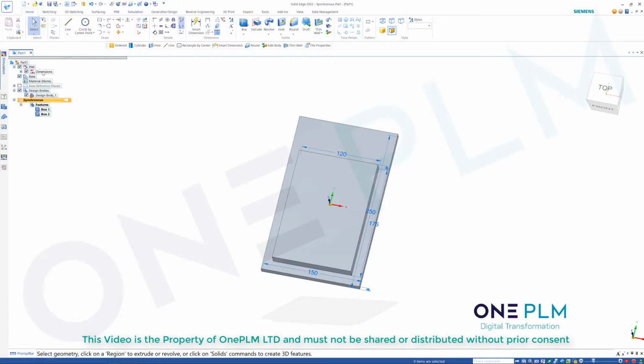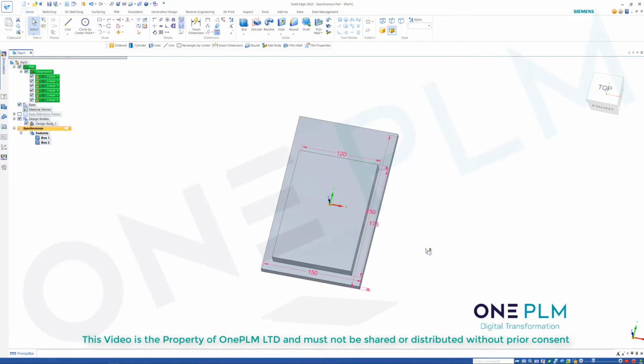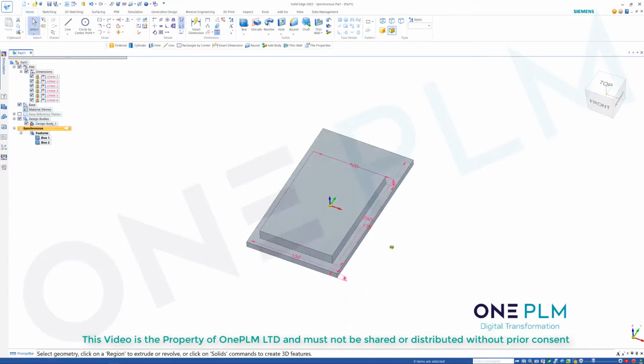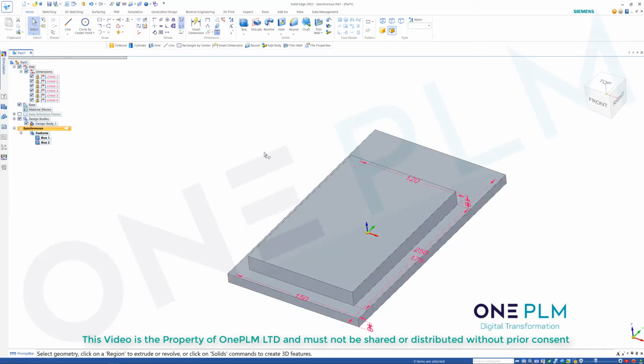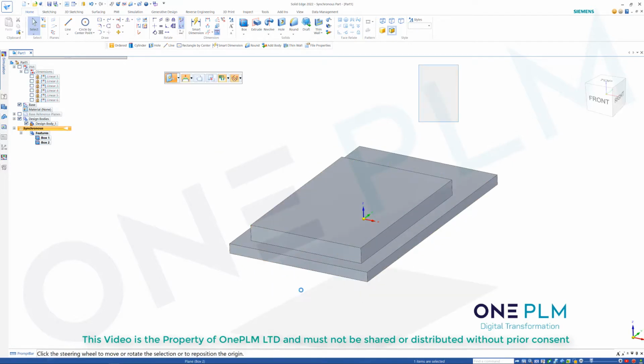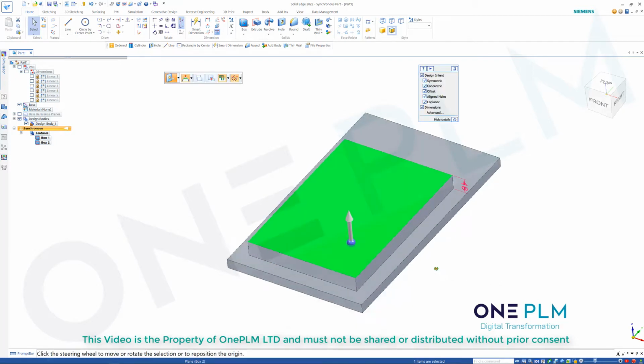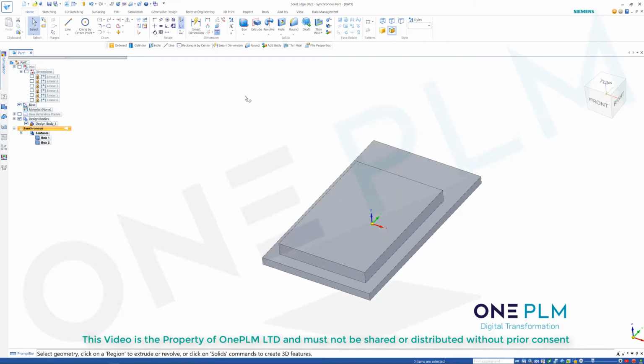A nice little thing I like to do is go up to my PMI, expand all those, shift select the top one, shift, the bottom one, right click, and then set that to driving dimensions. That locks all those dimensions, so we're not going to get spurious changes on them. You can also turn those off. If you're not a synchronous user, click on a face, and any dimensions that are valid for that face will pop up. So we don't need to have loads of dimensions on there.